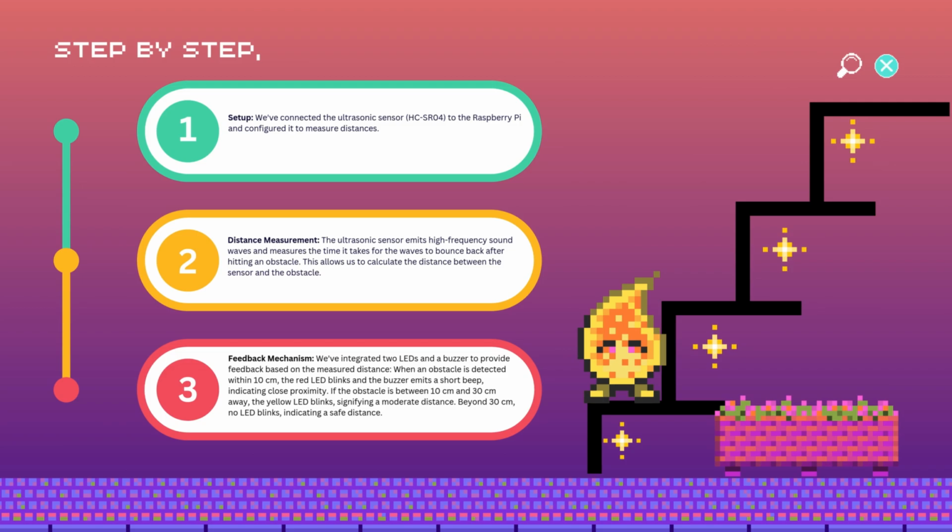Second is distance measurement. The ultrasonic sensor emits high frequency sound waves and measures the time it takes for the waves to bounce back after hitting an obstacle. This time measurement allows us to calculate the distance between the sensor and the obstacles using the speed of sound.